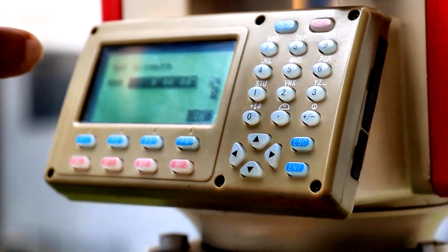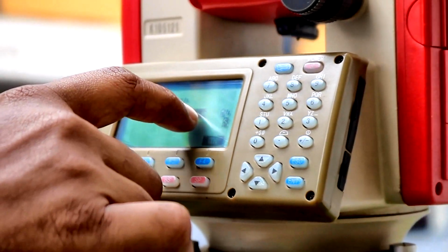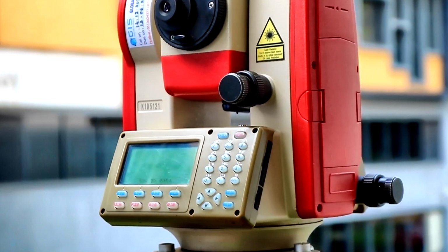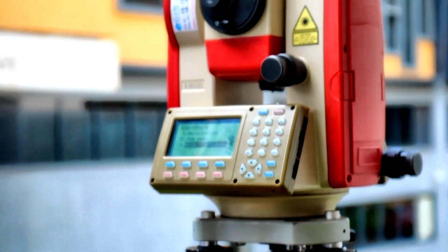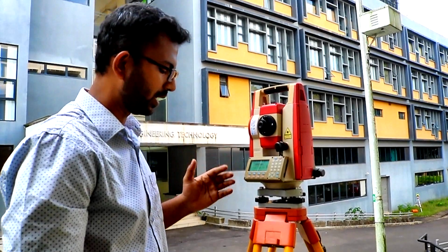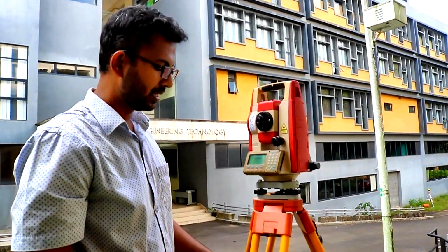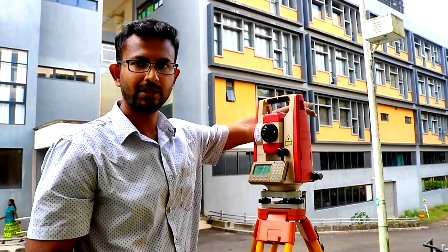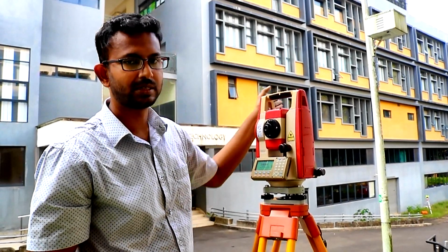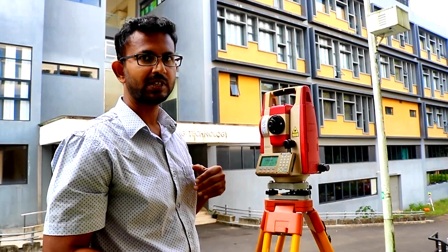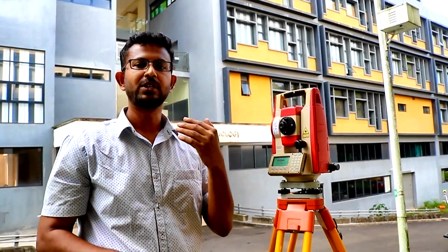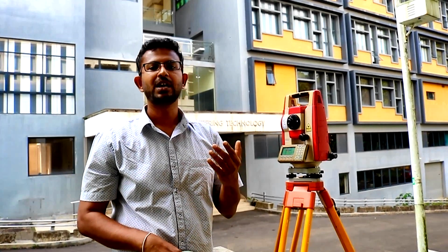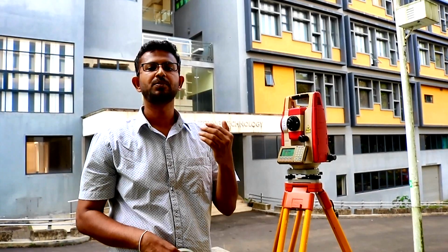Now I'm exactly looking north, therefore I can give as 0. So there already the 0 is there, but I give a 0. Then they ask if the 0 is okay. Yes, I press yes. Now I have oriented the instrument. Now I can take observations with reference to these two data. What are the data? The station data, the north, east and Z coordinate, and the direction where the instrument is directed, right? So that is called the orientation of the instrument using the Backsight Azimuth option. In our next video, we'll see how to orient the instrument using the Backsight NEZ option.